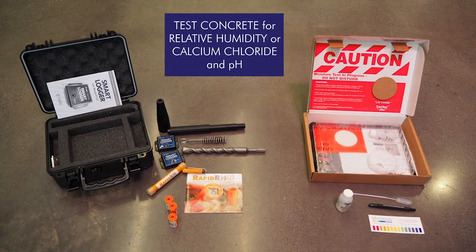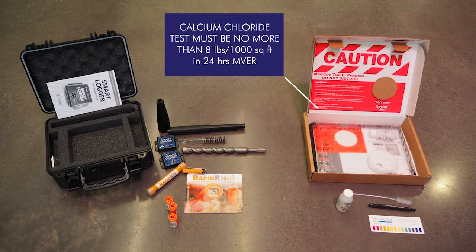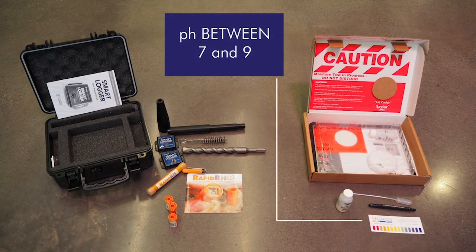Concrete substrates must be tested for relative humidity, moisture, and pH. Test results must not exceed 85% relative humidity or RH. The calcium chloride test for moisture must be no more than 8 pounds per 1,000 square feet in 24 hours, MVER, moisture vapor emission rating, and pH tests for alkalinity levels should register between 7 and 9.